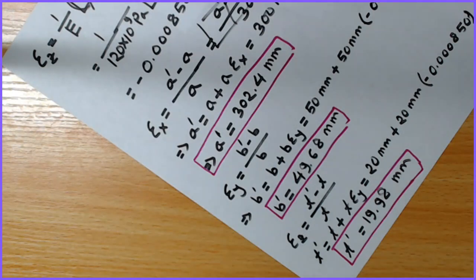Most of the real engineering problems on many occasions are 3D. So we need to understand how Hooke's law and the Poisson's ratios, and everything else, can be implemented in 3D. I hope after today's class you are able to apply Hooke's law to a 3D object which is subject to a tri-axial stress test.